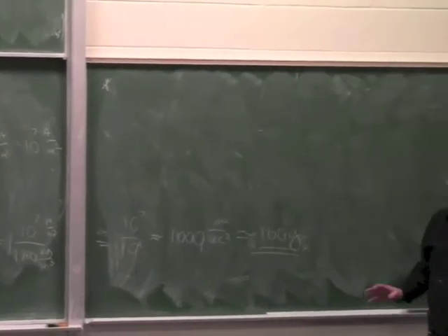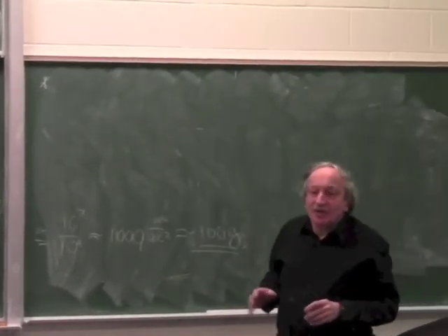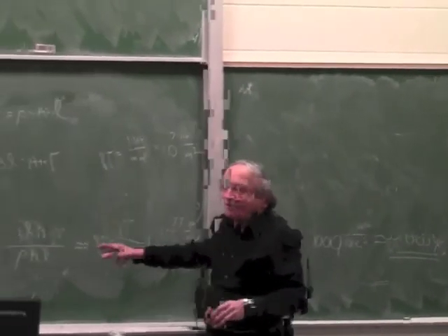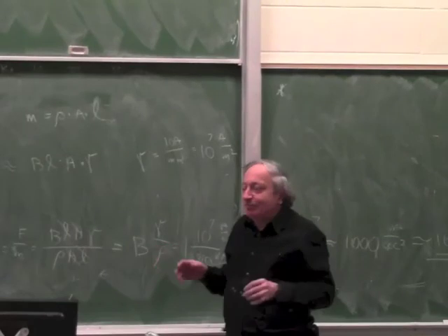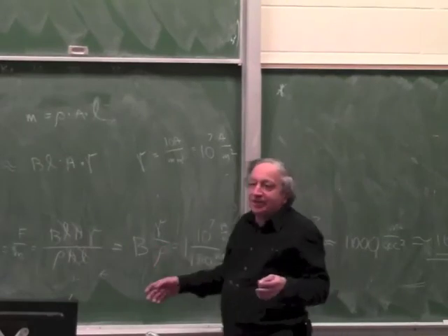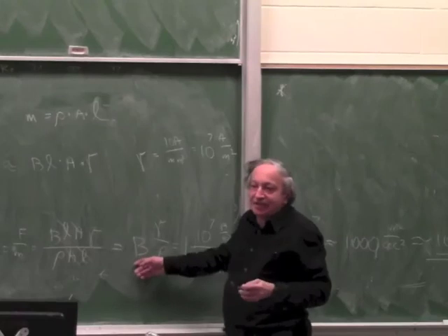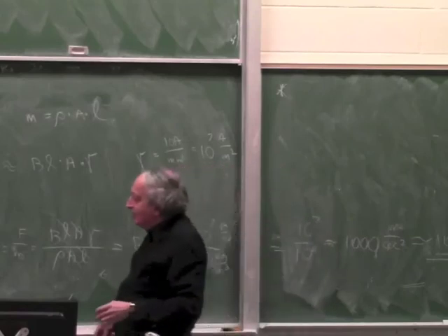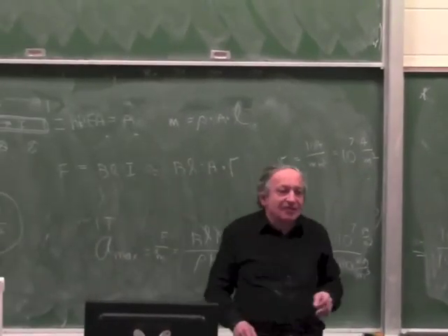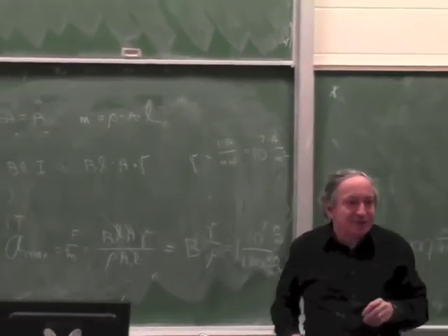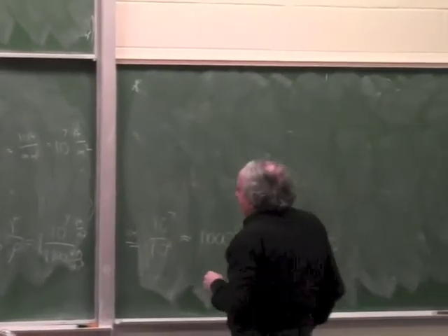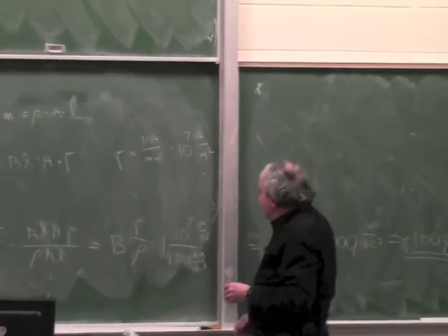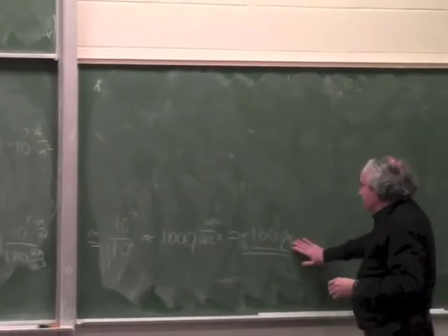So basically the bottom line of the story is that moving coil actuator performance is strictly limited by properties of materials. There's no big theory behind it. And B is limited by the quality of magnets we can get. If we take the best magnets we can get, like rare earth magnets, because we need an air gap for the coil, we are basically limited to 1 Tesla, unless you do heroic measures, like in MRI machines. And we take copper, which is a very good conductor with a certain power density, divide by its density, we get this. So what can we do better than that?